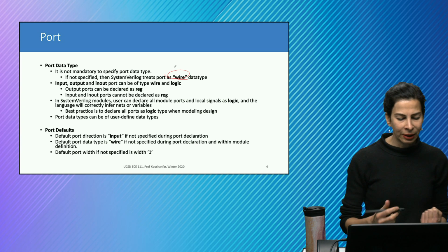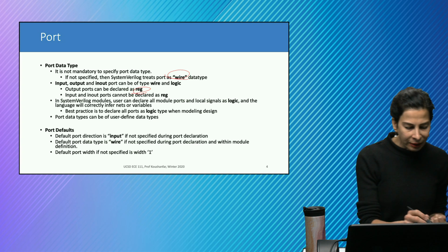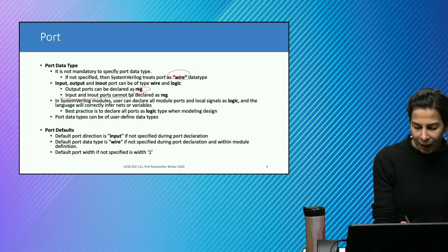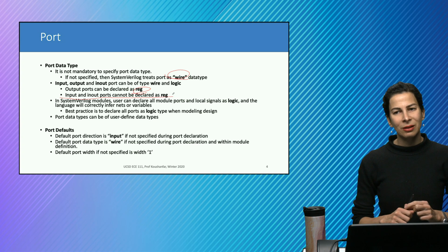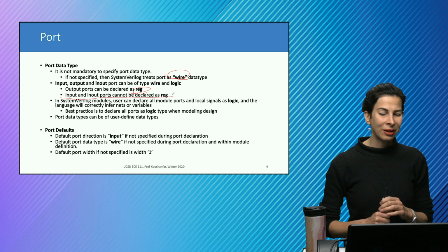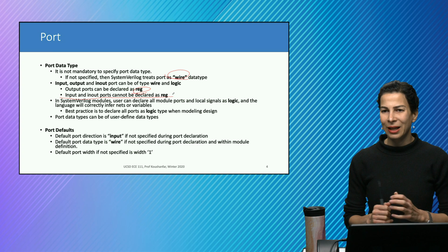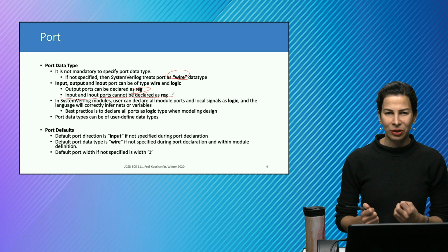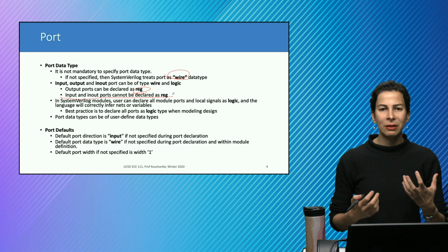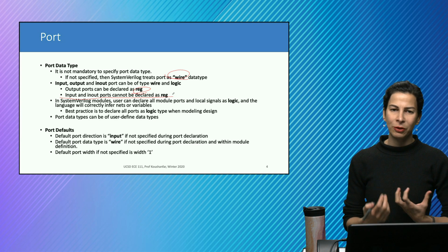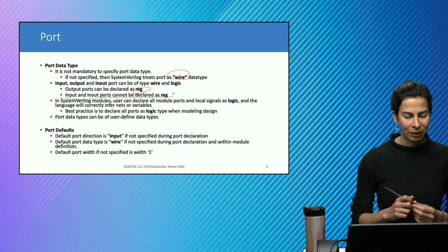You could also declare output ports as a register, but you cannot declare in-out and input ports as register. However, to reduce this confusion, as we discussed earlier, it is recommended that in SystemVerilog you use logic instead of register. When you declare logic, then you don't have this confusion or double checking of the input ports and getting errors.